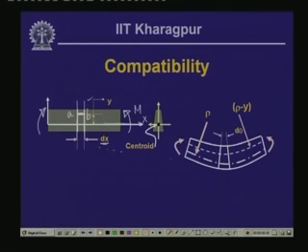So, under loading, let us say it undergoes deformation, and the deformed shape is something like this, which is the part of a great circle. Now, if we concentrate on this particular segment, which was originally dx, and let us say that it undergoes deformation, and let us call that along this particular length, this is ds, and this axis of the beam has a radius rho with reference to the center of this great circle. Now, the fiber AB here, this is A dash B dash, let us call it, after deformation.